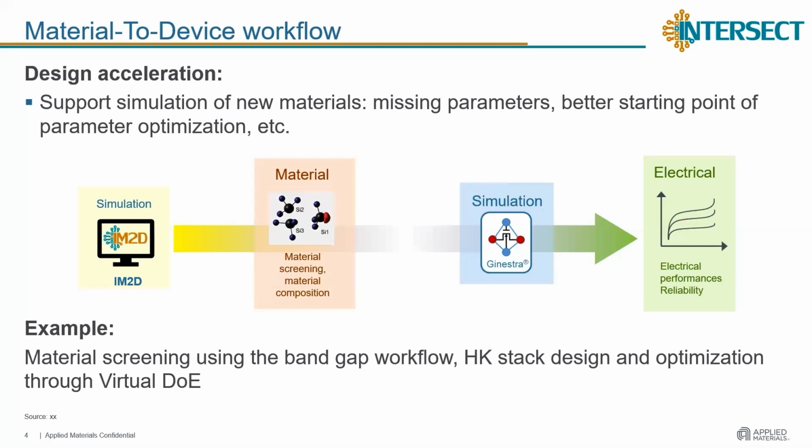In this particular case, I will compute the band gap for zinc oxide and provide it to the device simulator. There, I will consider a MOSFET device and I will test several materials in a layer of the gate oxide stack, running a sort of virtual design of experiment that will allow me to select the best candidate for further studies, or to, let's say, select 3 or 4 materials for which we want to perform a real design of experiment, saving money and time. So let's go back to the material property browser again.